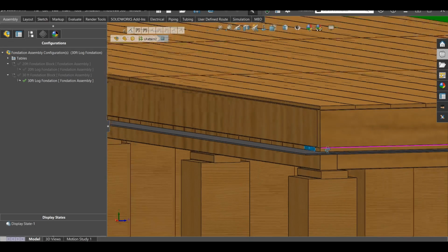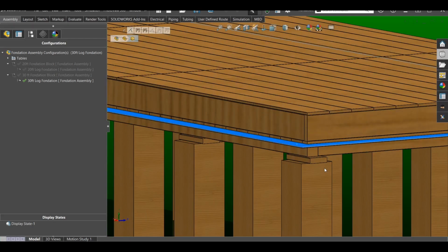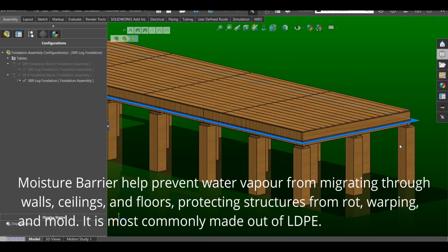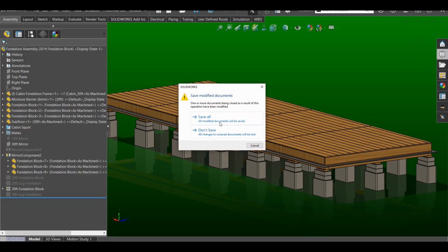My idea was to kind of seal up and add insulation. And then you get your plastic. It's like a big giant plastic tarp, basically. I'm not sure of the material. HDPE, probably not. It's basically a moisture barrier for a basement. And then on top of this, obviously you would build a wall. Now let's go see the wall.